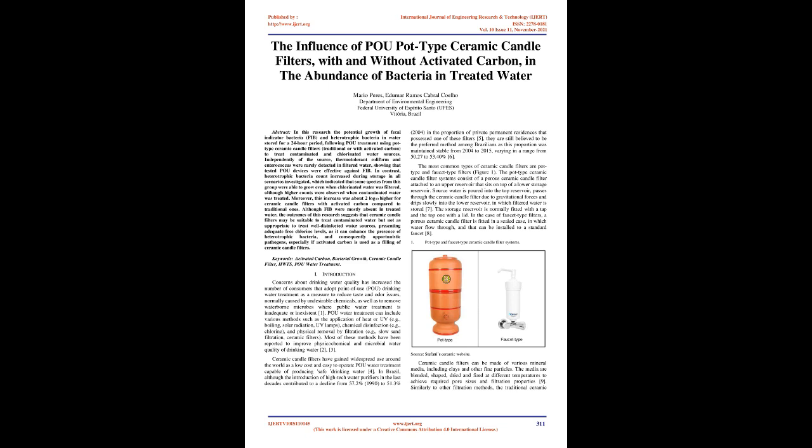In contrast, heterotrophic bacteria count increased during storage in all scenarios investigated, which indicated that some species from this group were able to grow even when chlorinated water was filtered, although higher counts were observed when contaminated water was treated. Moreover, this increase was about 2 log10 higher for ceramic candle filters with activated carbon compared to traditional ones.